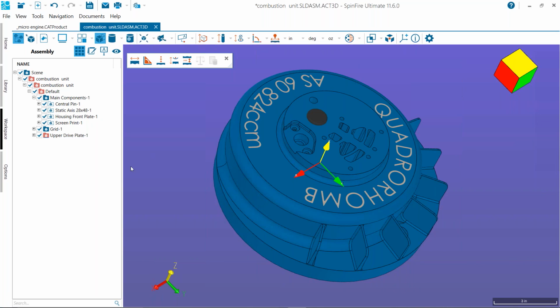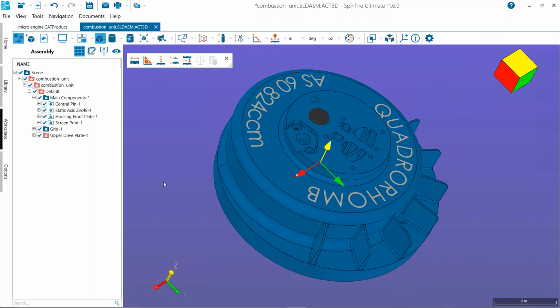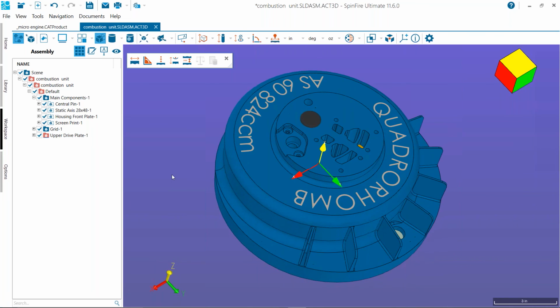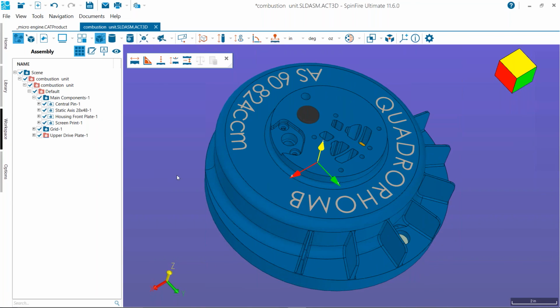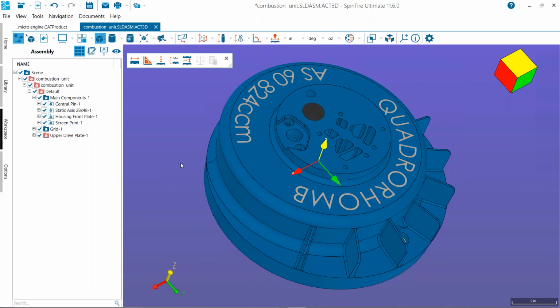Opening large files takes memory and CPU just to open them. Once they're open, it takes the graphics card power to display properly. So you may have 64 gig of RAM and a Xeon processor, but you have an onboard really low-end graphics card. It's going to open fast. It's not going to move around fast because the graphics card was not meant for 3D graphics. Could be that. I don't know without looking in that environment, but that certainly could be the issue.